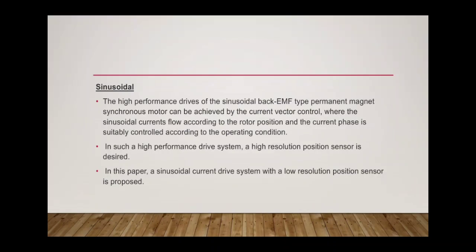Next, the topic is sinusoidal. The high performance drives of the sinusoidal back EMF type permanent magnet synchronous motor can be achieved by the current vector control, where the sinusoidal currents flow according to the rotor position and the current phase is suitably controlled according to the operating conditions. In such a high performance drive system, a high resolution position sensor is required. In this paper, a sinusoidal current drive system with a low resolution position sensor is proposed.